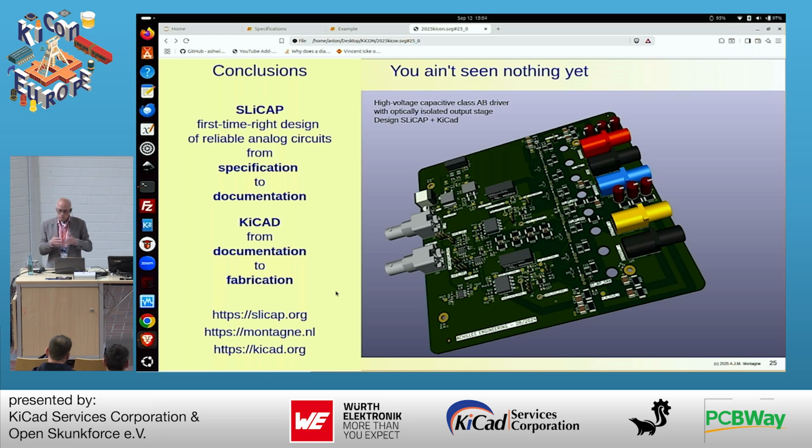You can equate this out, find the operating current and the geometry, and then switch to a BSIM model. Basically I use EKV, and then you switch to BSIM, and it's within 5%. So yeah, it's huge.